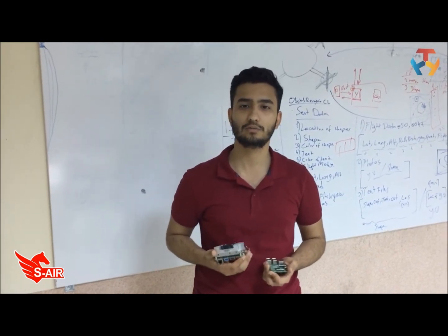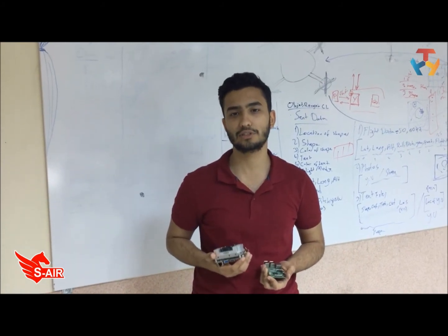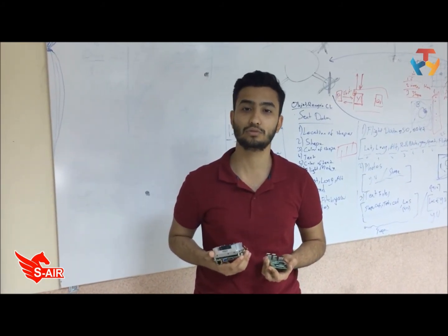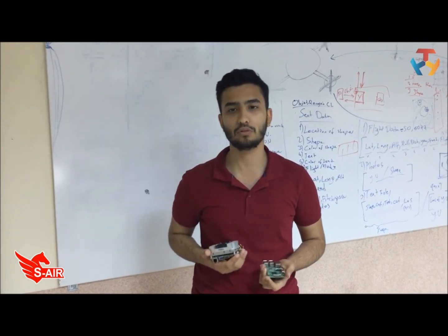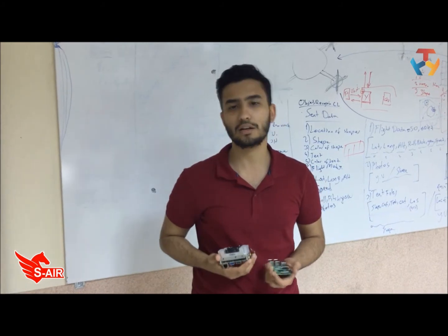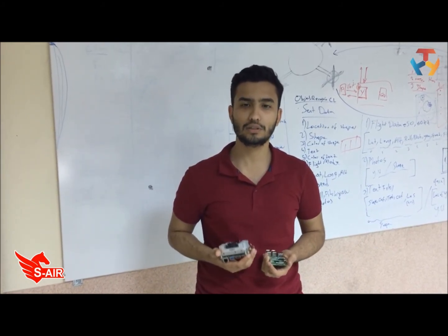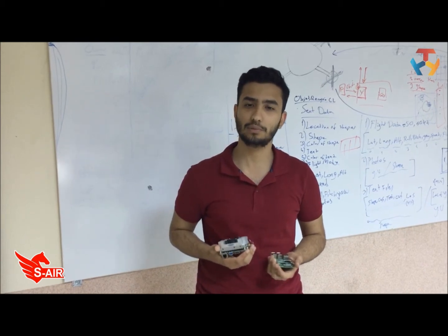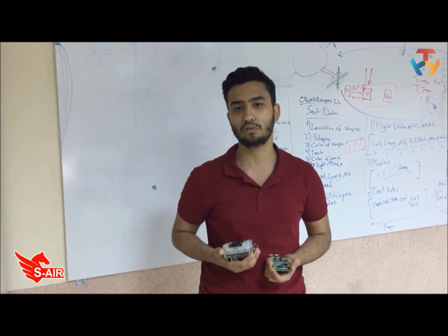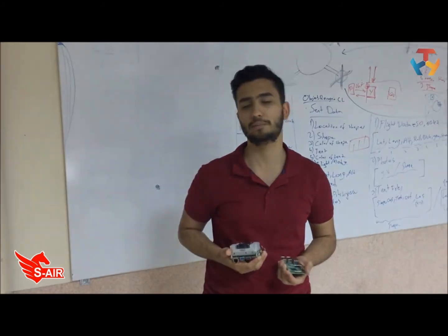During the flights made with Raspberry Pi 3, the CPU of the card was insufficient for the image processing algorithm used during the mission. Tinkerboard also gave the same results as Raspberry Pi. That is why Jetson TX2 was chosen for the missions. Jetson TX2 has a 64-bit CPU with 6 cores and 8 GB RAM with enough CUDA cores for deep learning.